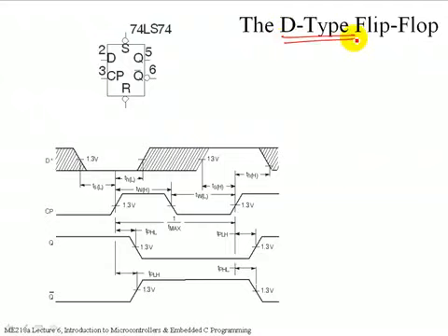The simplest of those is called the D-type flip-flop, or just a D flip-flop. For now, let's skip the set and reset inputs. They're just extra control lines that are made available on this particular implementation. The essence of the D-type flip-flop is a D input, a Q output, and a Q bar output. Notice the bubble, that's actually badly labeled, I realize. That's just a Q, but with the bubble, it guarantees that Q and Q bar are always going to output the opposite state.